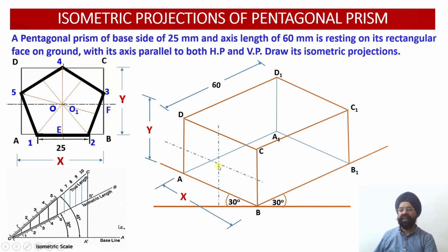Then the next thing is evaluating the axis point in the front face and the axis point in the rear face. In the front face, how I have located this axis: I have measured the distance between corner A and this point E, right? So this was there in the geometric construction. Once again, all these distances are isometric. So this distance AE, this isometric distance, I am going to mark over here. This will give me point E.